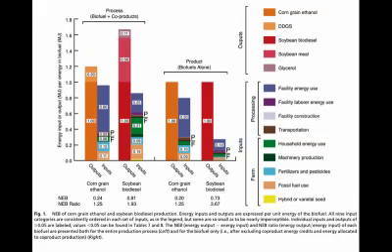Let's take a look at a life cycle analysis study. Now, this is an energy life cycle analysis, not an emissions and not a financial. We're looking at the energy on the y-axis for 4 different processes, and this is megajoules of energy in the biofuel. So here we're looking at corn grain ethanol and soybean biodiesel, and we're producing 1 megajoule. Here is the production, megajoule output in the biofuels.